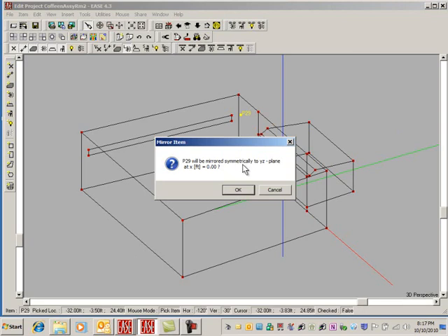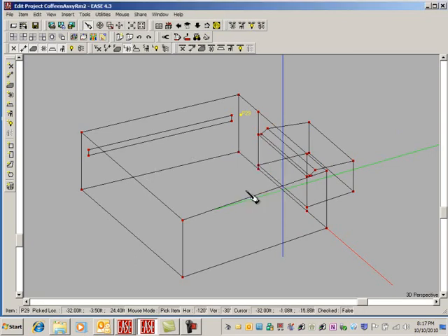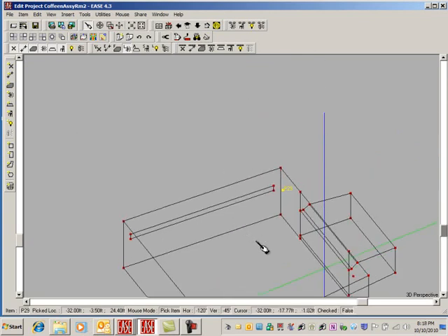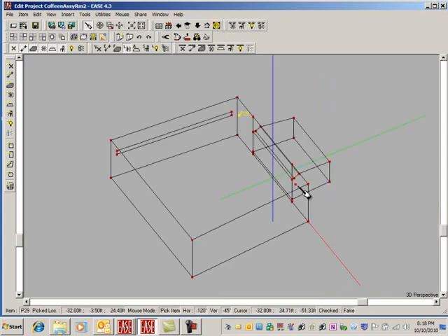There it is. Now, one way to make this first panel would be to make a line here and then extrude it up the distance of the panel, which is 12 feet at an angle of 10 degrees up, and in the 0 degree horizontal plane. So what if I make a line, an edge? We'll insert an edge from here to there. Okay. Now we can see that a little better.